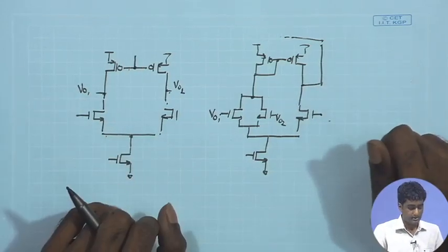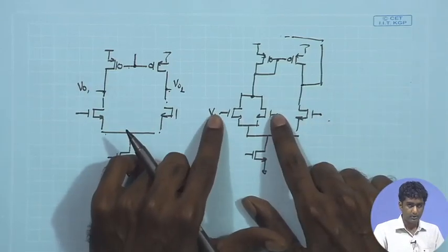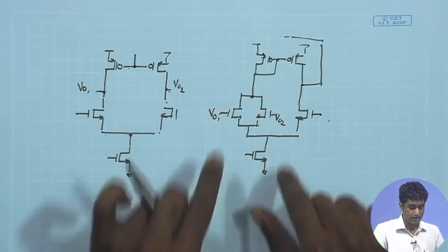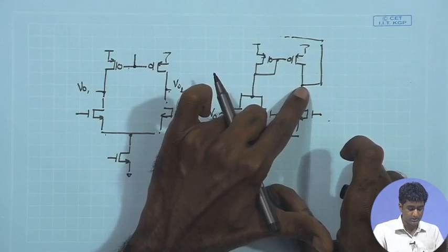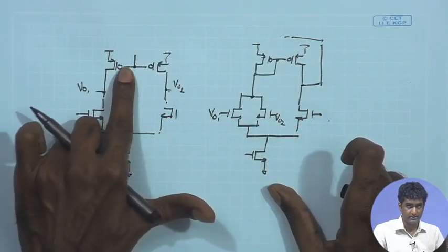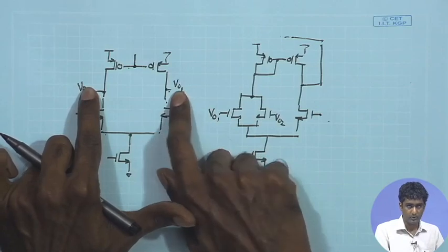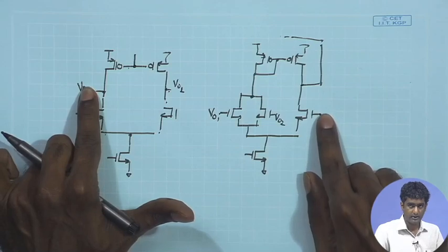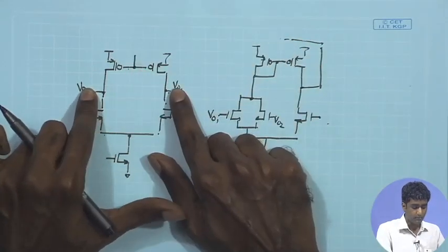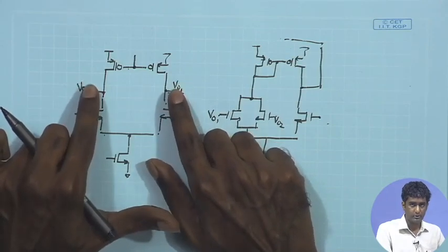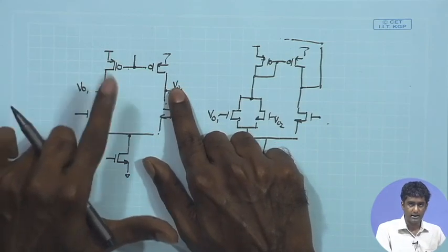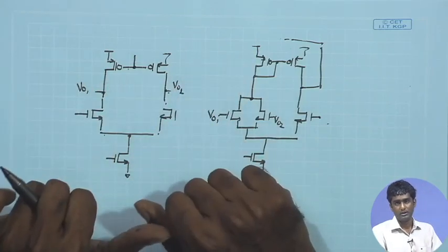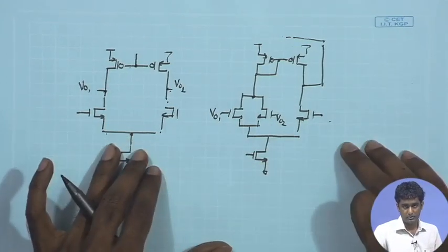The other option is that, as we have discussed in the theory session, we can open the loop over here. So, we can disconnect the input of the error amplifier from the two outputs, keep the connection between the output of the error amplifier and the PMOS as it is, and then observe the final output coming over here. Under that condition, we will be applying an AC signal over here, and of course, since it is going to be a common mode operation, both the outputs will be changing in the same fashion, and therefore, that behaves as my final output, that is the A beta factor. So, observing this signal is equivalent to observing A beta times the input signal. So, these are the two ways in which we can do it.